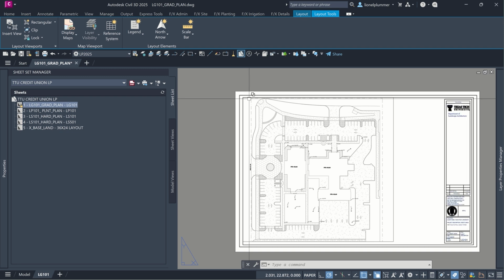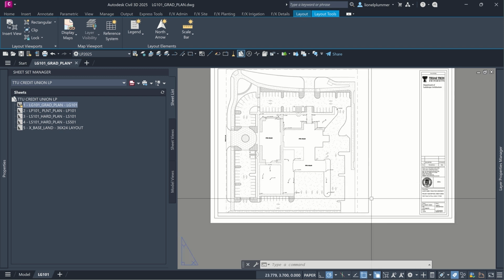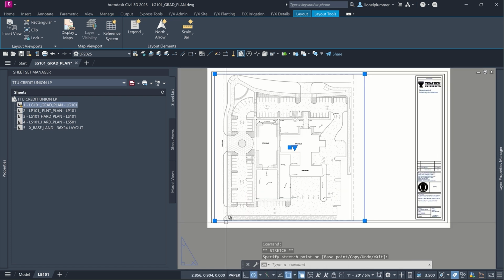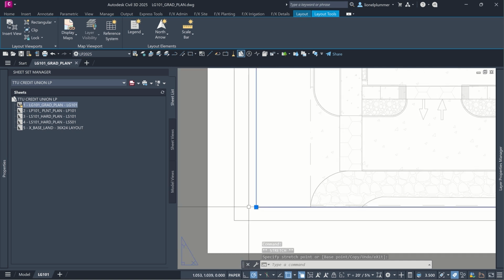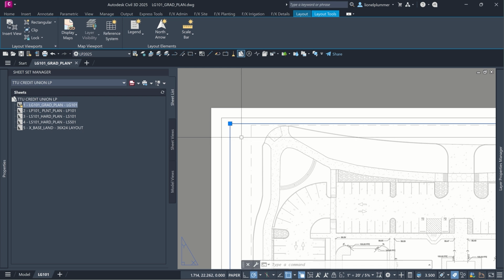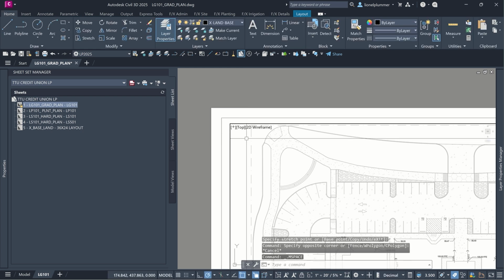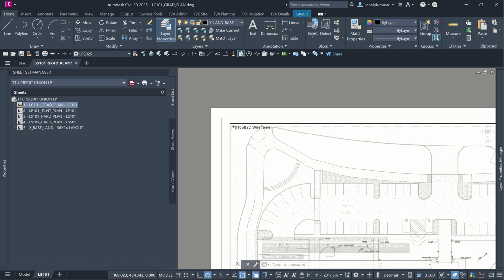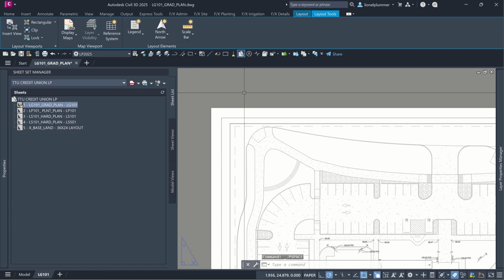The other thing is we have a very, very tight fit here with the scale. So we need to make this viewport come all the way down to this internal border. It's on there, and it's on up here. Now let's double click in this one. Make sure you're unlocked in a 20 scale, and then move this over to the corner and up about as high as you can get it. It is snug.